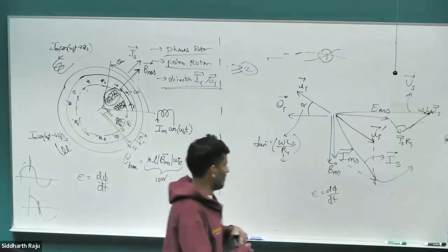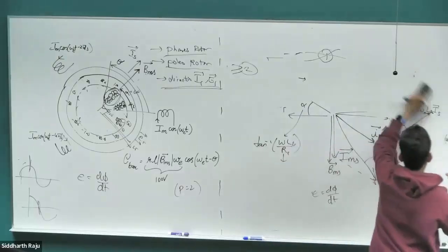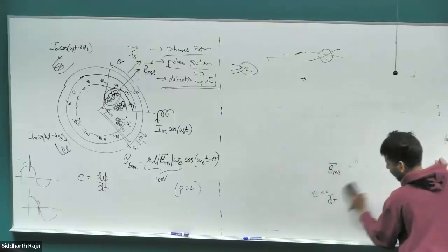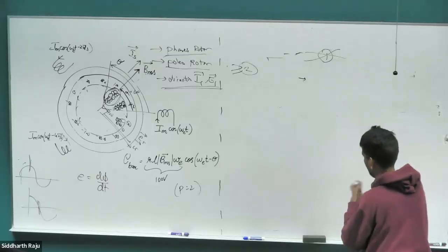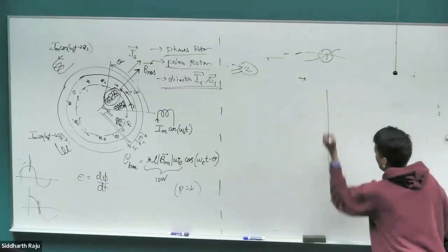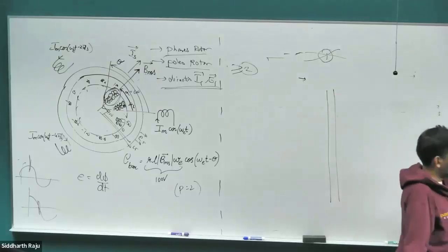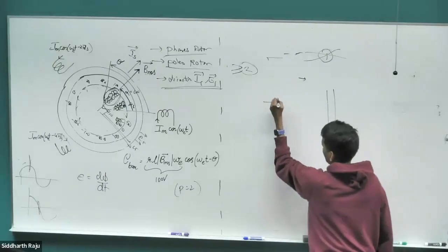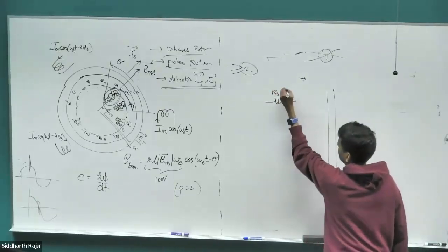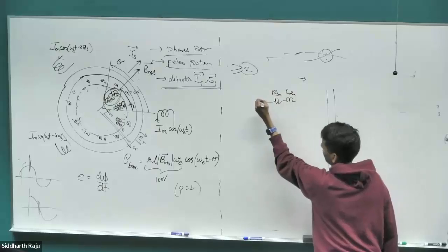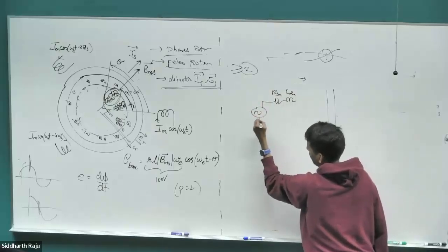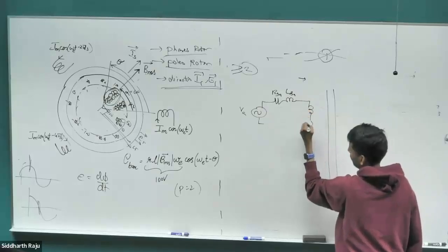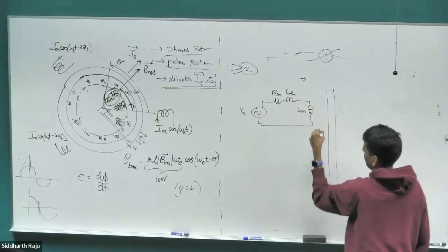So if you want to do the same reduction of this three-phase system to a one-phase system, it will be good to have the rotor be modeled as a three-phase system as well. So let's look at what's going on. This whole diagram that I did is just a one-phase transformer. In our case, we have three phases. So we have some resistance, some leakage inductance of A phase, and some voltage source on the A phase. And then we have some magnetizing inductance.